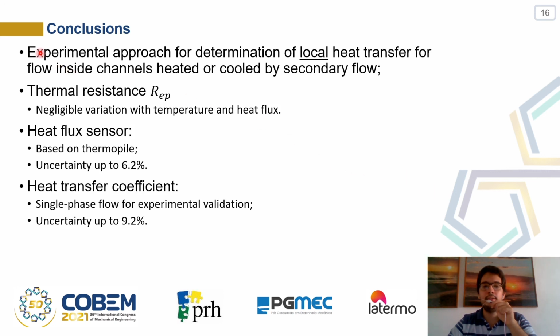In order to summarize, this study presented an experimental approach for determination of the local heat transfer coefficient for flow inside a channel with a heat flux sensor based on a thermopile. The thermal resistance of the epoxy layer presented negligible deviation from its mean value, indicating its independence from operational temperature and heat flux. Uncertainties up to 6.2 and 9.2% were estimated for the heat flux sensor and heat transfer coefficient.